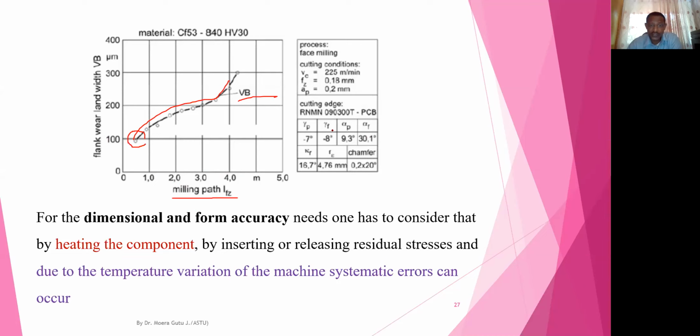Here you will see, only when this research is conducted, the angles, the relief angles, the rake angles, and the clearance angles range are here. When you do research, you also have to mention what relief angle, what cutting clearance angle, and rake angle you have used. You have to mention also the required surface finish you obtain, the VC, the cutting velocity.